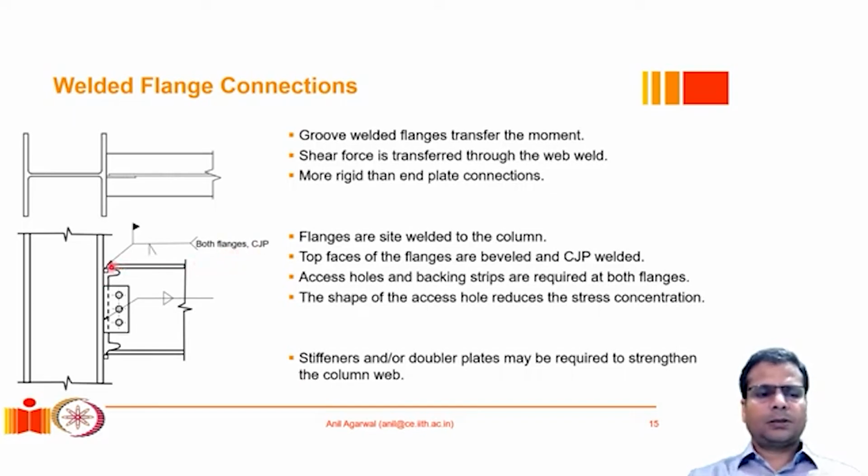And typically such welds are complete joint penetration welds. Complete joint penetration weld is critical because it provides the required level of ductility, which is usually missing in a partial joint penetration weld. When we pull this flange apart from this flange, if it's a partial joint penetration weld and there is no other component resisting opening of the root, a PJP type of weld would perform very poorly under this situation. Therefore, in such situations, complete joint penetration is very critical.